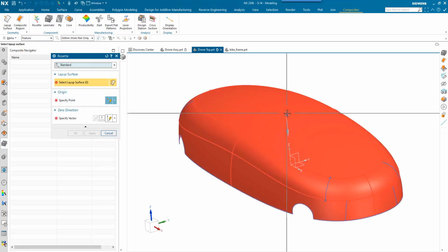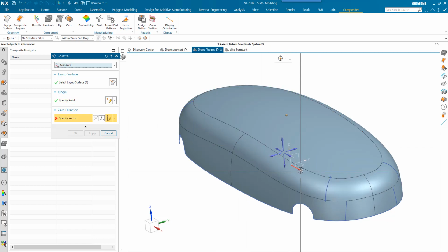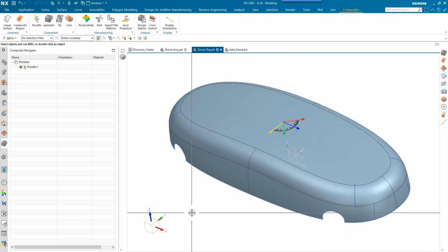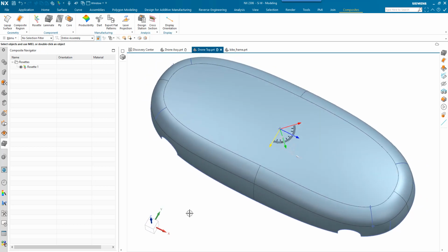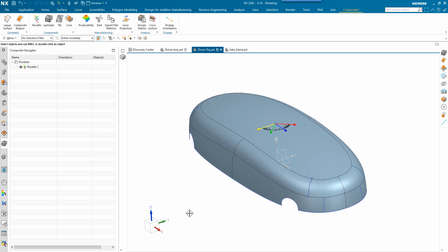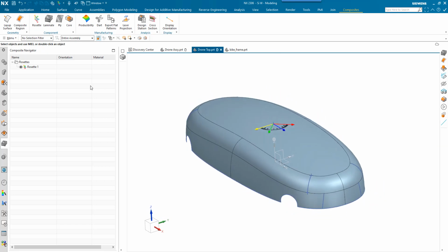A rosette is what we would normally use to define the orientation of the plies. And when you've got carbon fibre, which is basically a woven sheet with each of the weave directions being at 90 degrees to each other, when they put the plies one on top of the other, they tend to orient them at 45 degrees. For strength, so you've never got two sheets running in the same direction, ideally. So this is used to help define the ply orientation.